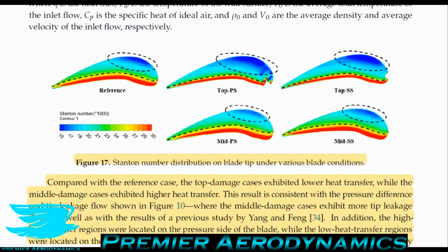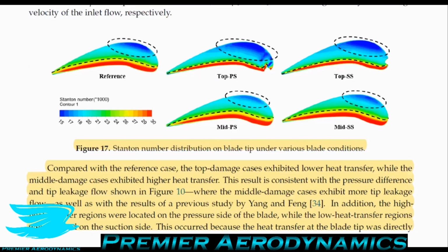that compared with the reference case, the tip damage cases exhibited lower heat transfer, while the middle damage cases exhibited higher heat transfer. This result is consistent with the pressure difference and tip leakage flows shown earlier, where the middle damage cases exhibited more tip leakage, as well as the results of the previous studies, which showed a similar sort of thing.